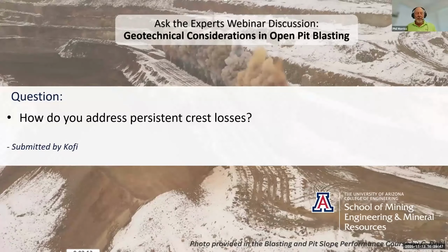I would add that sometimes the bench face angle or the batter angle can impact all of that, especially when you get into flatter bench face angles, and you need to start thinking about how you disperse that energy. If it's all loaded near the toe, you don't have a whole lot of energy up here. You can get either overhangs, or in one weird case I ran into, they were pushing the blasting further and further into the slope to avoid that, and then damaging the slope.